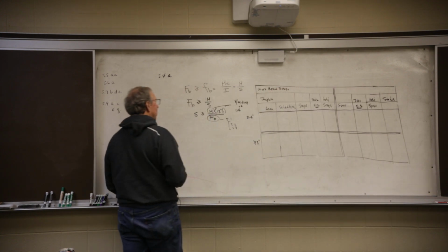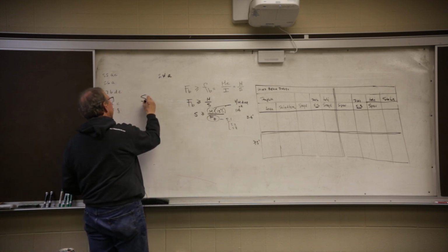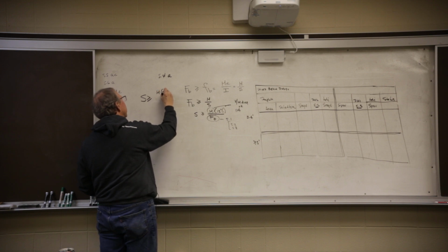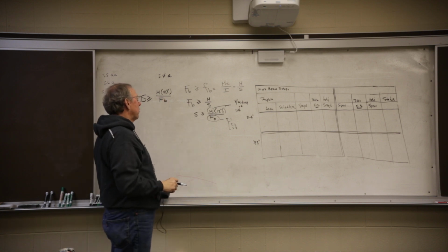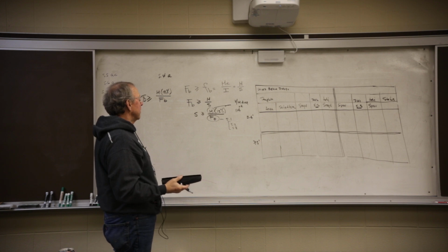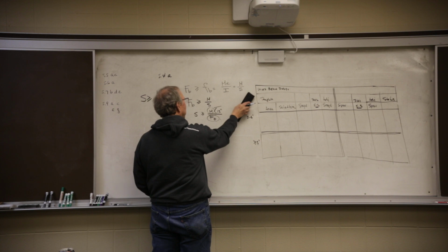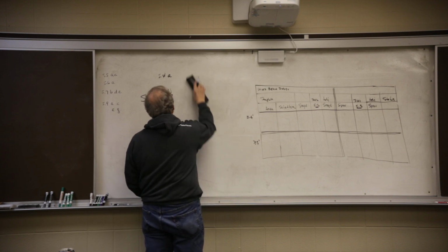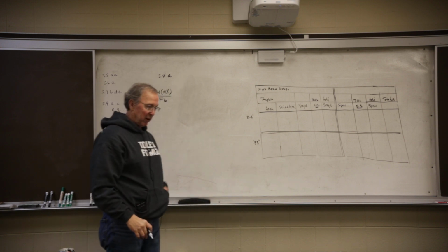Okay, so there's our equation. This is what we need. My equation is a section modulus has to be greater than or equal to M times 12 inches per foot divided by FB. So we get M by either drawing a shear and moment diagram or using page 114. We get FB by going into the table 5.1 and putting it into the formula. So let's do one. While you guys are doing 5.4b, I'm going to do 5.4a.